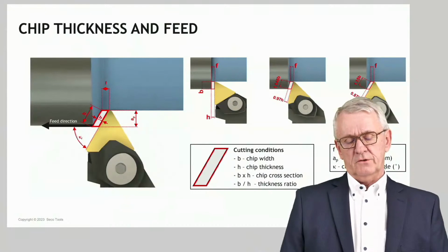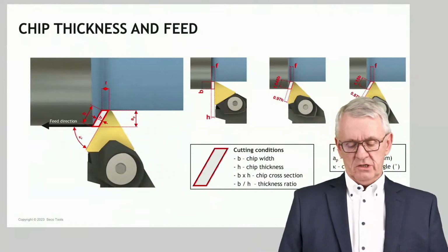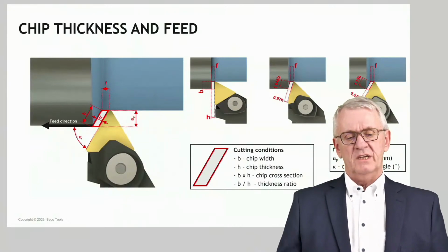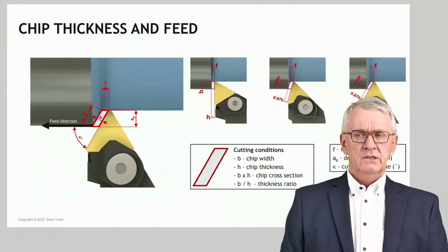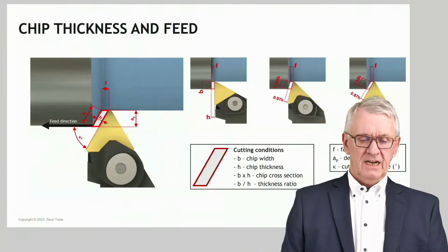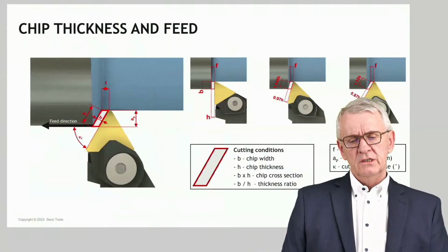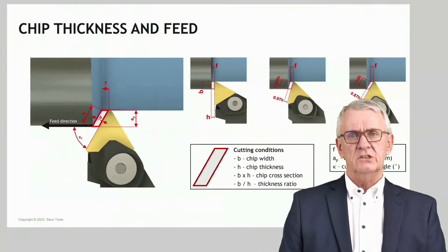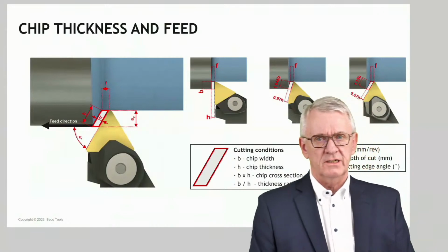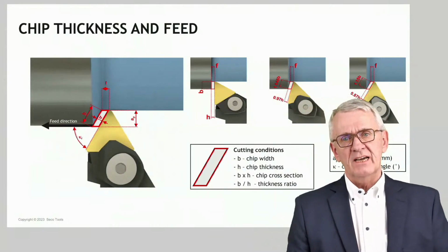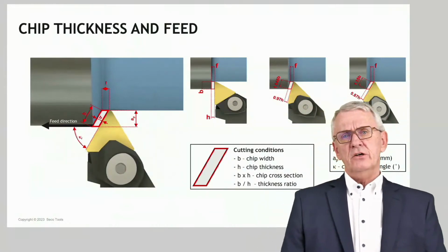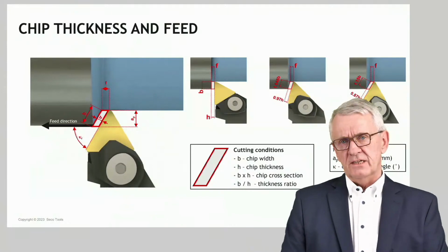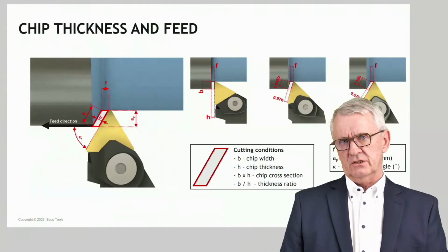Once they are determined for a certain workpiece, for a certain cutting tool, that's how we program them, and that's it. How a cutting edge works, the physical phenomena that are going to happen around the cutting edge, the wear we will see on a cutting edge, the tendency for vibrations, refer to the technology or are influenced by the technological cutting conditions.